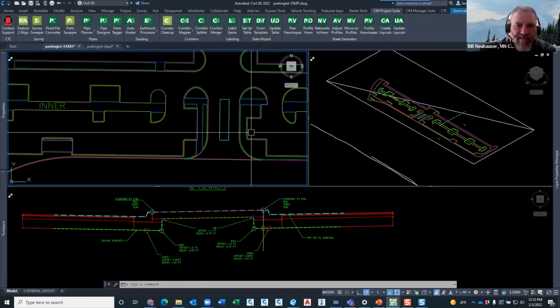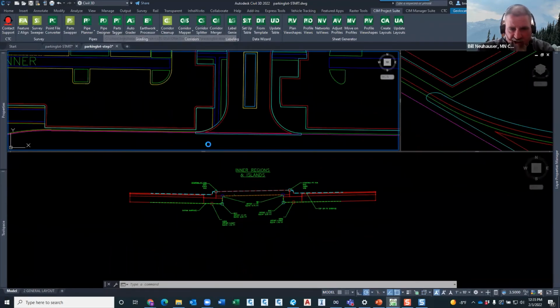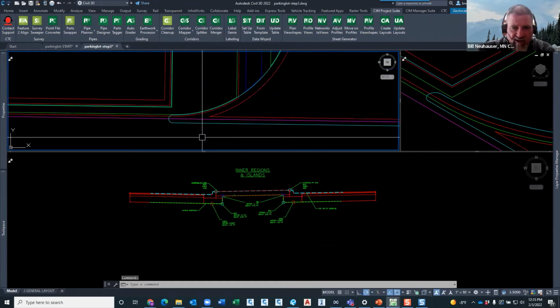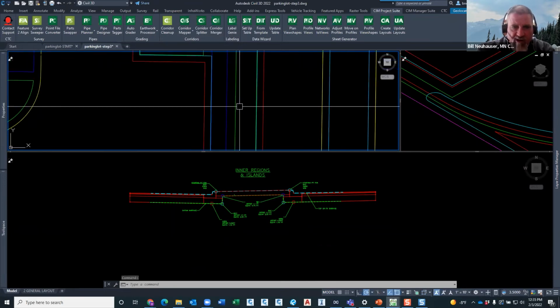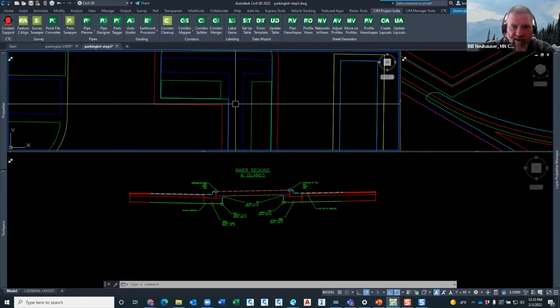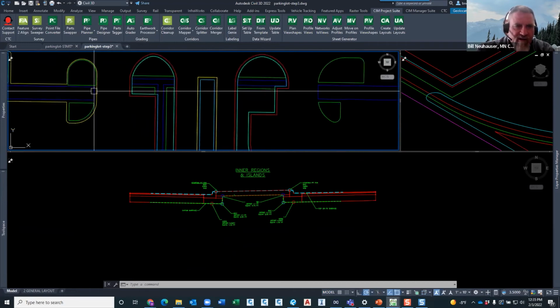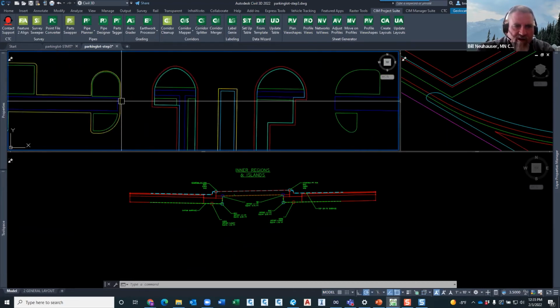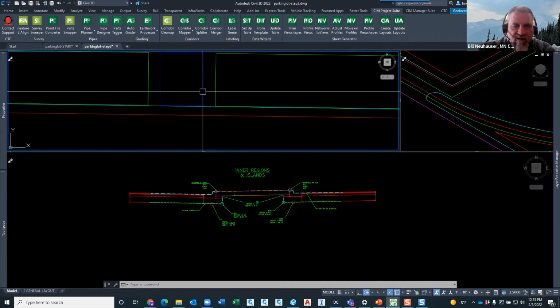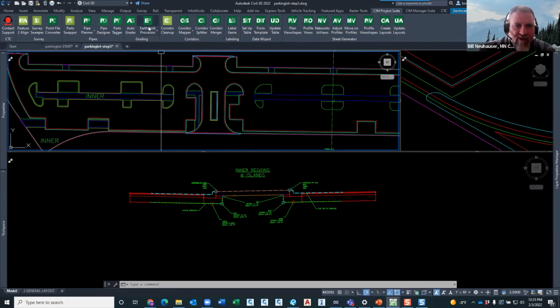Now, next thing here, so I'd run through that whole process, and magically, I'd get this drawing. And as I zoom around here, again, my biggest thing is I want to make sure things are offset correctly. And if I zoom around, you can kind of see what's going on here. Okay, so once you've got everything offset correctly, then I'm going to go into the Earthwork processor and go calculate earthworks.